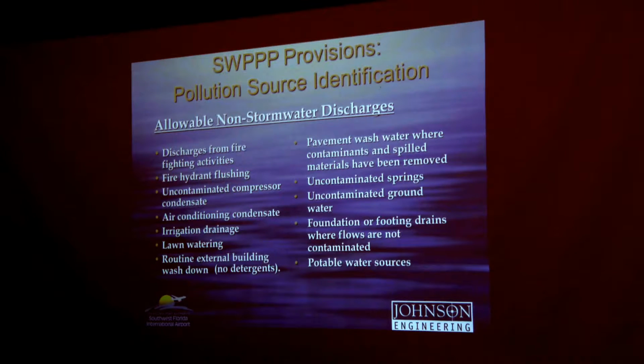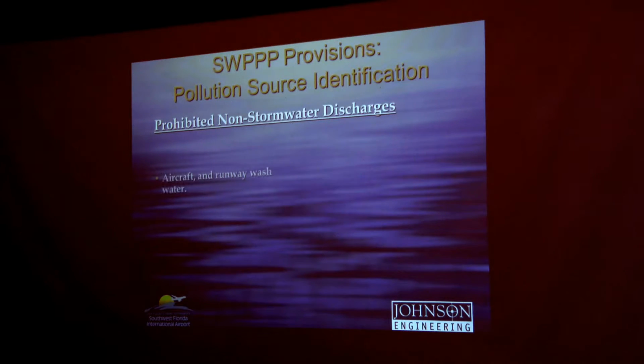There are some non-stormwater discharges that are allowed, but you can see it's a very specific list. Discharges from firefighting activities are included, along with fire hydrant flushing, uncontaminated compressor condensate and air conditioning condensate, irrigation drainage, lawn watering, routine external building washdown, as long as no detergents are used, pavement wash water, where no contaminants are present, uncontaminated springs or groundwater, and uncontaminated foundation or footing drains, along with any potable water source.